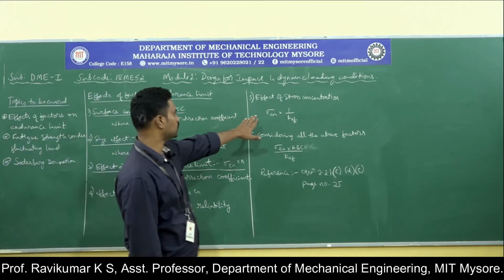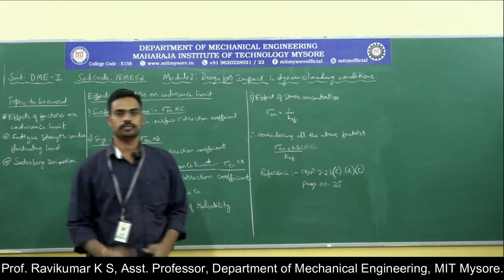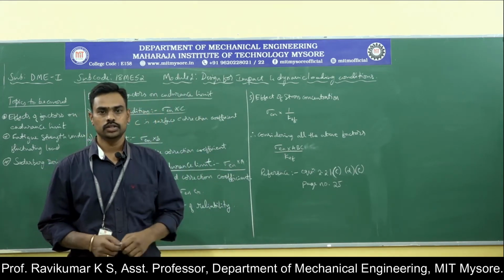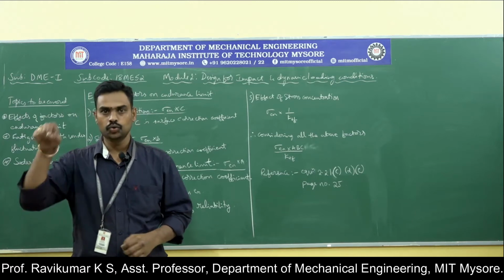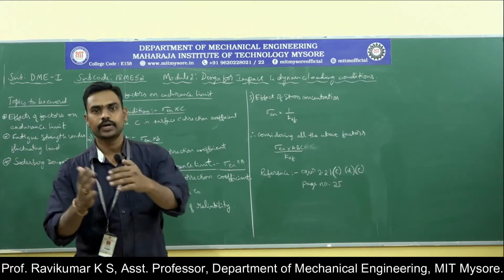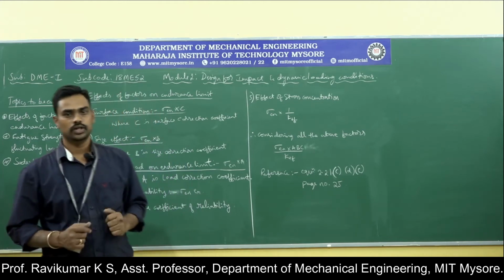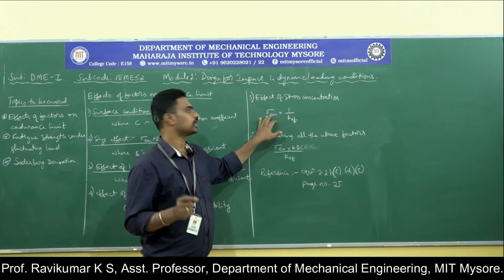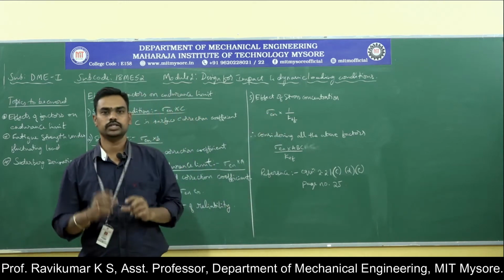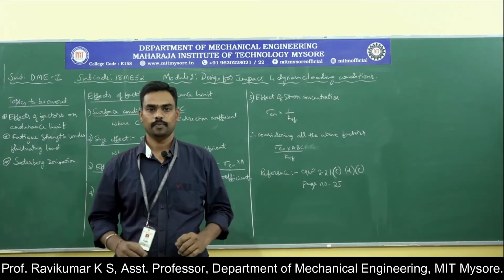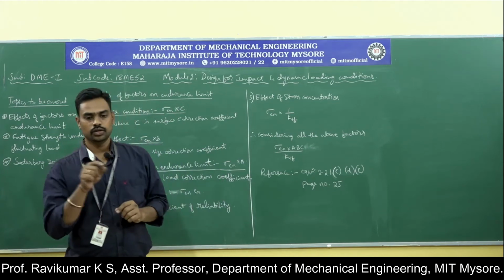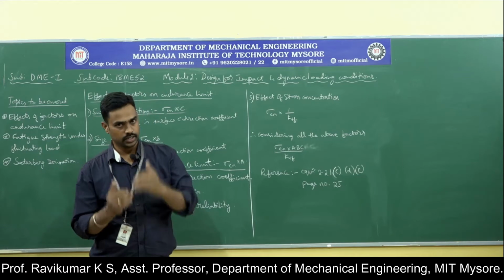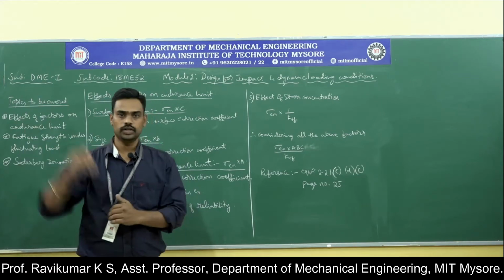Similarly, if there is stress concentration, meaning if there is a discontinuity in the material like a notch, or a groove, or a stepped shaft, then obviously stress concentration comes into the picture because there will be a change in the area. If there is a groove, then the area is going to change at that particular point. If the area is decreased, then the stress is obviously going to increase.